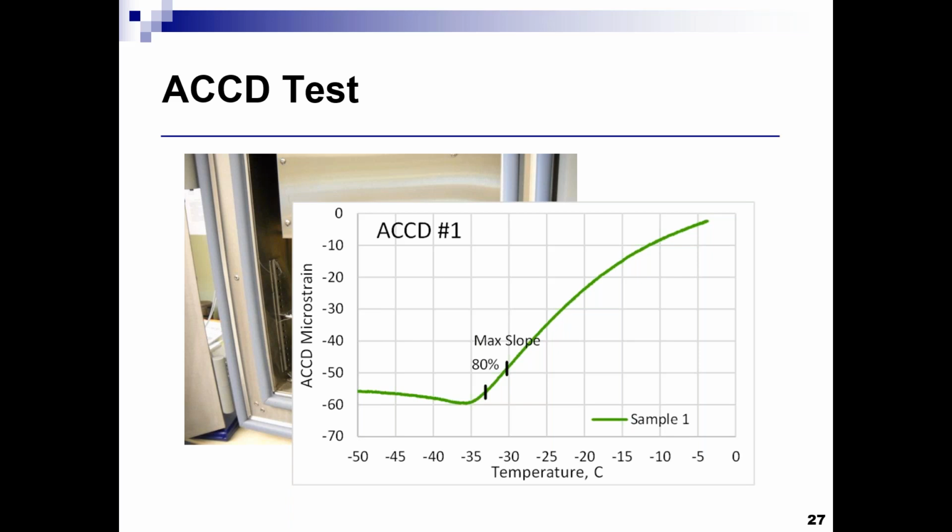Now, asphalt mixture performance with regard to low temperature cracking is highly affected by the PG grade of the asphalt binder, because low temperature cracking happens due to the shrinkage of the asphalt mixture when the temperature goes down. So it's really a tensile stress that is controlling that failure mechanism. And since it's a tensile stress, the glue that is holding the aggregates together is going to play a significant role in determining the performance of that asphalt mixture.